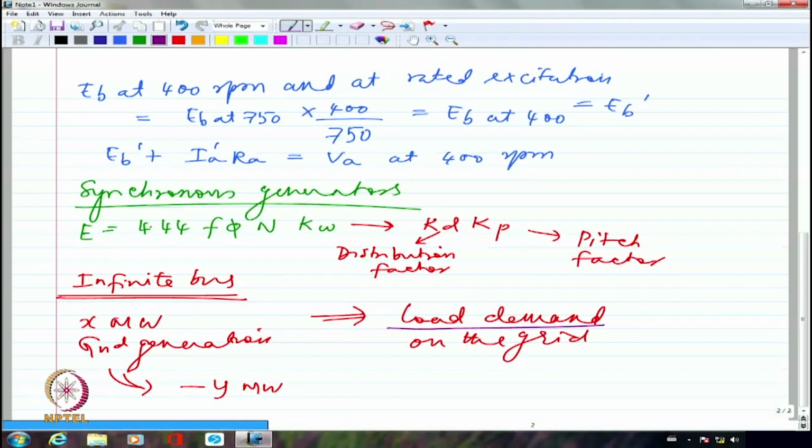So what I am trying to tell you basically is, the infinite bus is infinite as long as things are all fine. If many generators conk out, or many loads for some reason conk out, which can also happen if one particular feeder is tripped completely, a feeder being a transmission line which feeds power to some industrial area probably, then something conks out and I'm going to have a power imbalance.